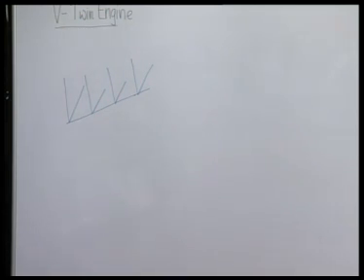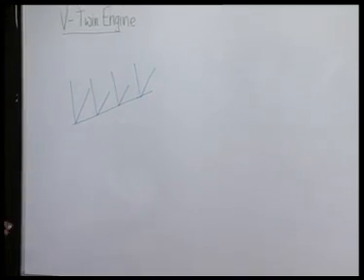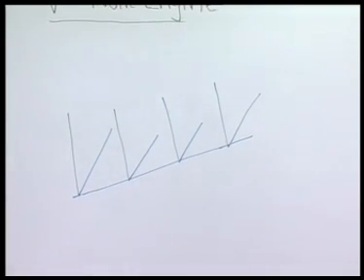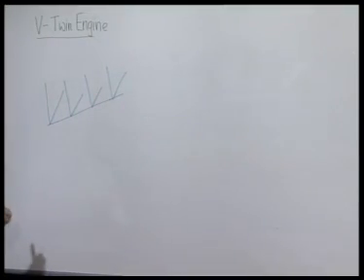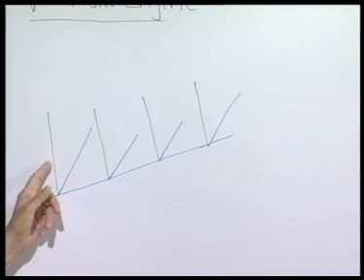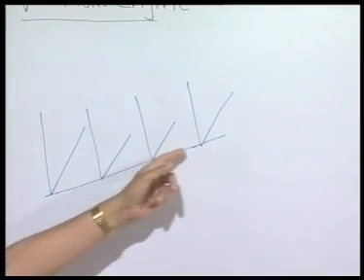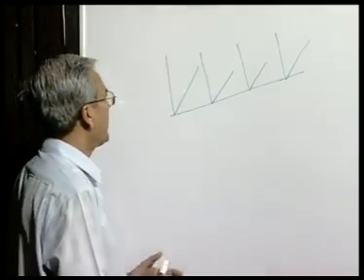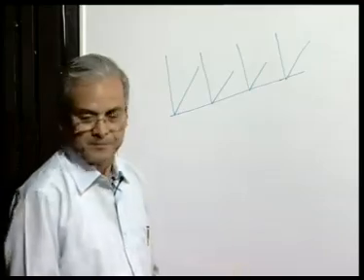So, as in the last session I showed that for a 6 cylinder 4 stroke cycle engine, it is possible to arrange the firing order in such a manner, that means the crankshaft will be of such shape that the primary and secondary both forces and moments are completely balanced among themselves. So, here also you will find by suitable arrangements such an engine, maybe it will be an 8 cylinder engine, each V will have 2 and there are 4 V's. It will be possible to completely balance up to second order the unbalanced forces and moments.